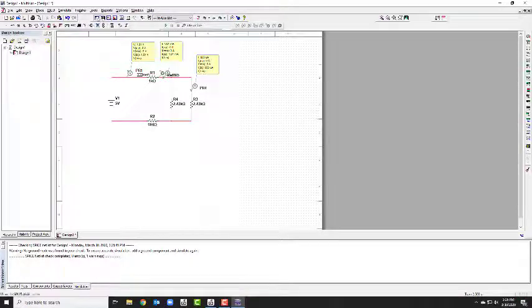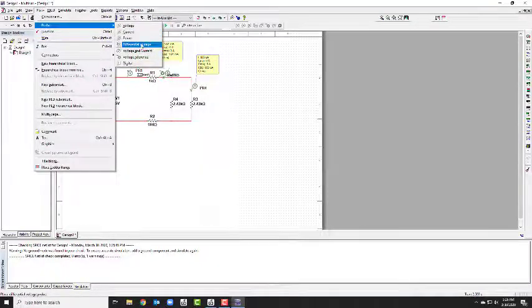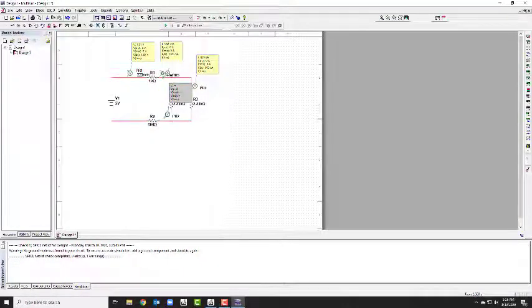We'll hit stop and place another probe, another differential voltage, one on this side of the resistor and then on that side. Then move this down, that's fine the way it is. And then run it again. Okay, yeah, 1.44 volts. That looks more reasonable there.